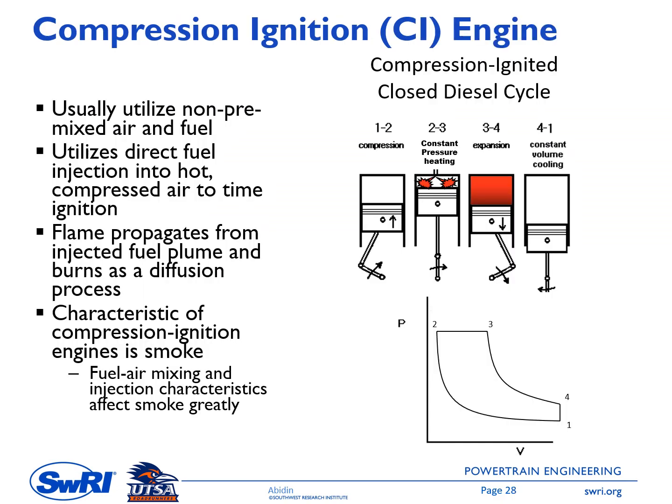Next one is the introduction of the compression ignition engine, or what is called a diesel engine. In this diesel engine, usually it utilizes non-premixed air and fuel. In this case, only fresh air is introduced to the engine, or sometimes it is fresh air plus EGR. This is EGR, exhaust gas recirculation.